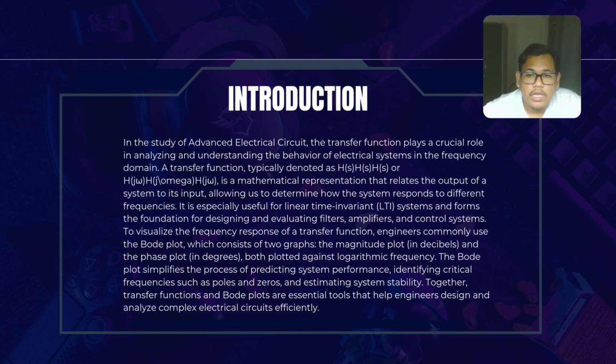It is especially useful for linear time-invariant (LTI) systems and forms the foundation for designing filters, amplifiers, and control systems. To visualize the frequency response of a transfer function, engineers commonly use the Bode plot, which consists of two graphs: the magnitude plot in decibels and the phase plot in degrees. Both plot against logarithmic frequency.